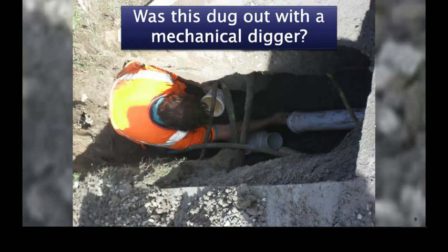So that's why you need a spotter and/or pre-identifying the services, and then your spotter is also the hand digger who's going to carefully dig around those services. And you actually want to dig down the face of a trench, breaking it away, rather than dig from the top down, because otherwise you can put the shovel through the service as well.